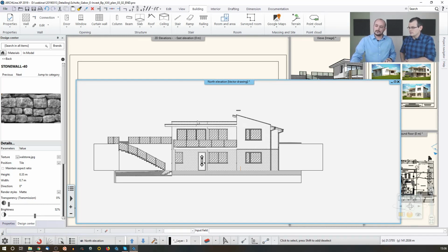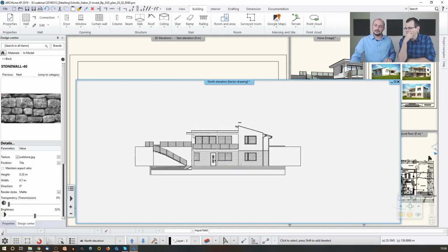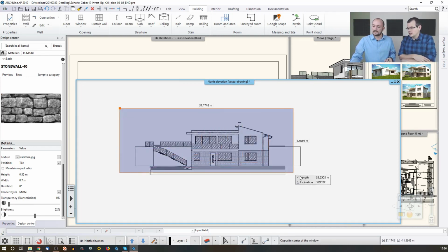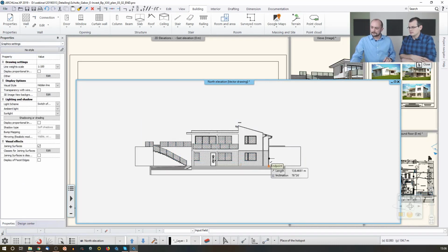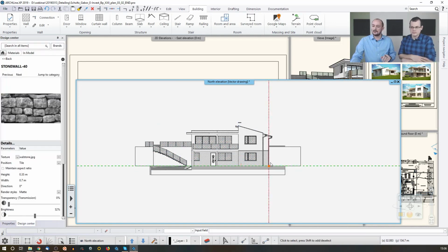This time we would like to show you how to turn this dynamic content into a line drawing, which you can handle just like other 2D drawings. In that case, you just select the content that is generated, and then you just Ctrl+C copy that. You should always set up a reference point, which is this point now. It's not that important which point I clicked. It will be the pickup point of that drawing, and this is where I can set it up to place someplace else.